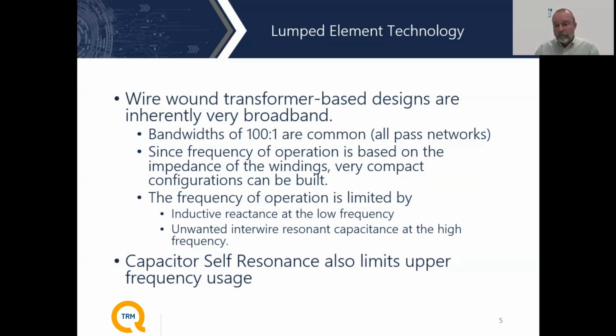They perform well. Since they are all pass networks, they actually work very low in frequency, and they really physically aren't that large, as long as the inductor that you're building is high enough to give you the required X sub L to have the transformer work in a transformer mode as opposed to an inductor mode, a little above what I was planning on talking about today.